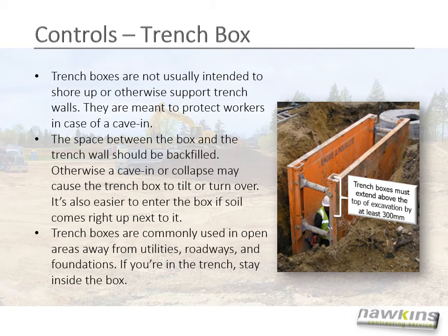It's also easier to enter the box if soil comes right up next to it. Trench boxes are commonly used in open areas away from utilities, roadways, and foundations. If you're in the trench box, stay inside the box. And just like shoring, trench boxes must extend above the top of an excavation by at least 300 millimeters.